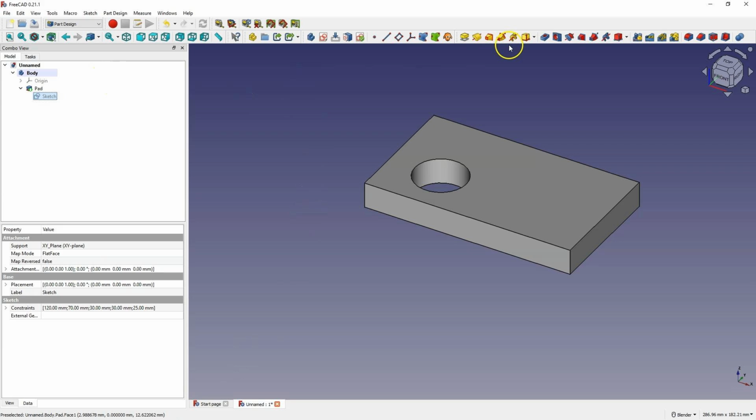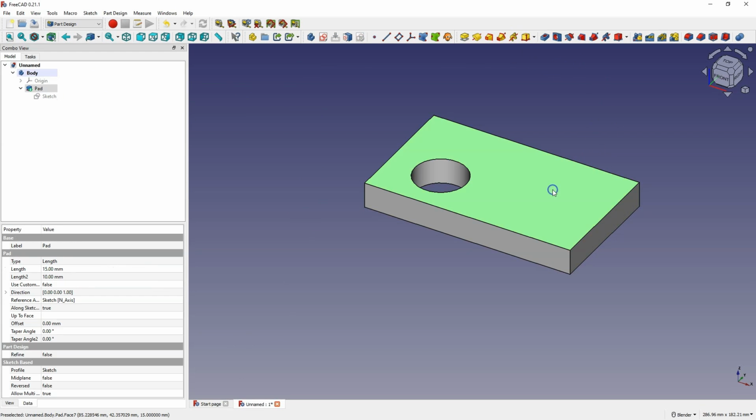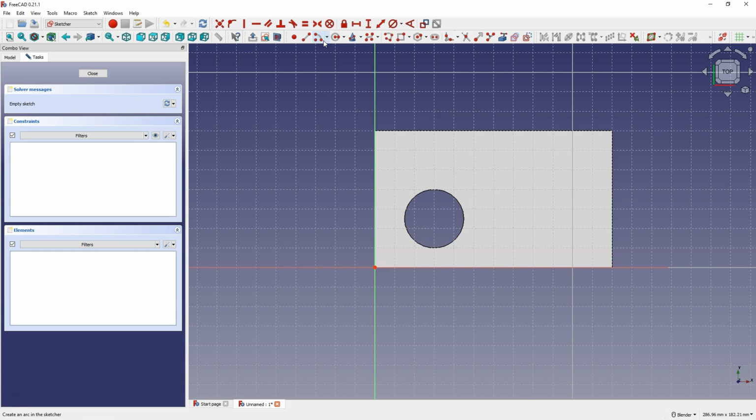And here, to create another piece of the solid, we can create another sketch on this wall. And to do that, select this wall and select Create Sketch. Now I'd like to create another sketch that will be related to this solid, and I select Draw Rectangle. And I would like the first corner of the rectangle to lie in this corner of this solid.